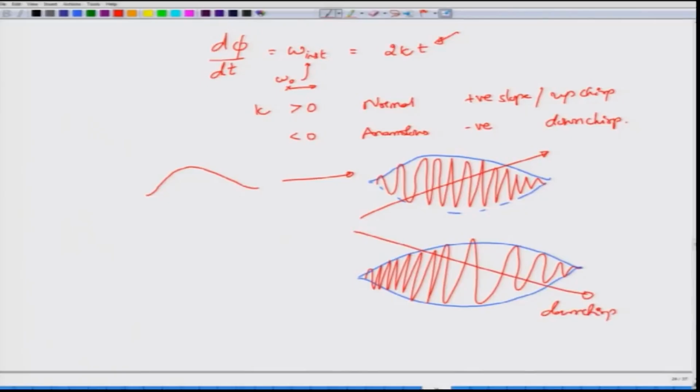So, the effect of dispersion on the pulse that is propagating, which is initially unchirped and Gaussian, is to retain the Gaussian character, and in the absence of losses have the same energy as the input, but this pulse at the output would have broadened out mostly, and it would have also acquired chirp. This effect is not desirable, and mitigating it occupies a lot of interest in fiber optic communication system design, something we are going to see in the future modules.